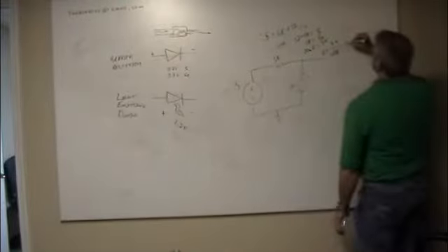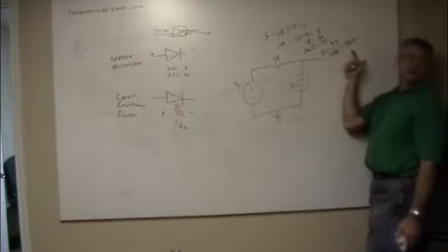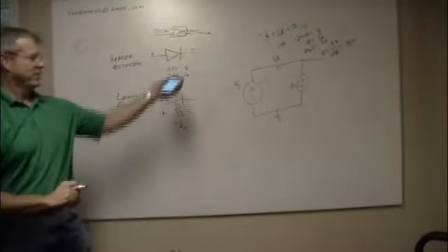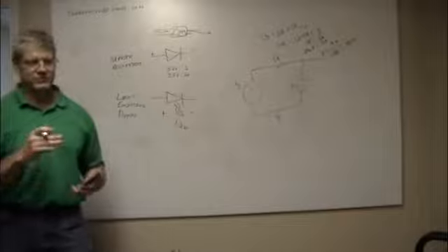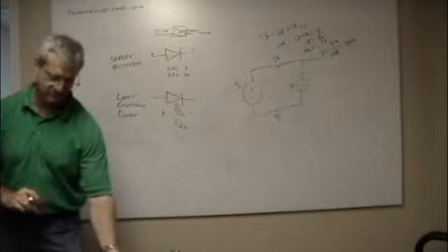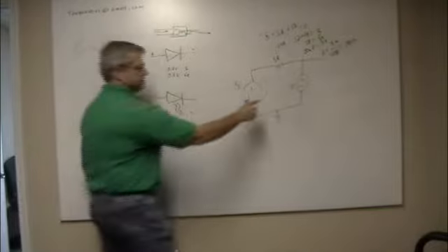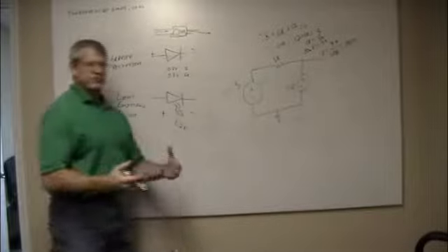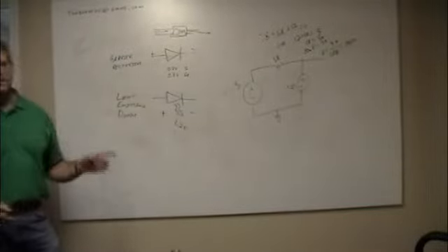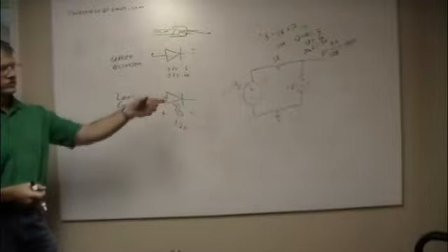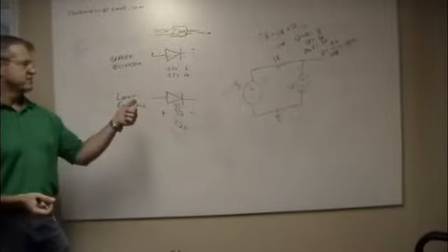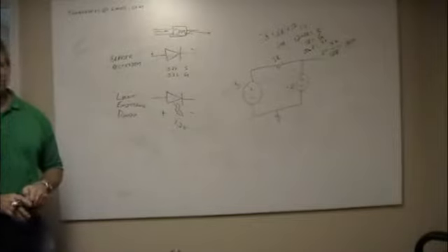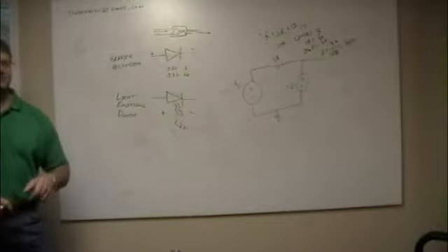Do you remember what I said 2 weeks ago? About 200 ohms. 200 ohms is probably the most common resistor you're going to see because we always use them for LEDs, or 220, 230, 300, somewhere in there. So again, same logic, it applies. This is the minimal math you need to do. If you know that you're always going to be using a 5-volt supply, and you know that most of your LEDs are about 1.2, invest in a bunch of 220 ohm resistors, and they'll get you 85 or 90% of your projects done for little lights.